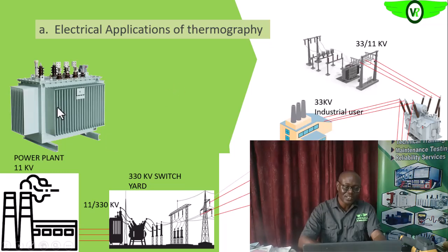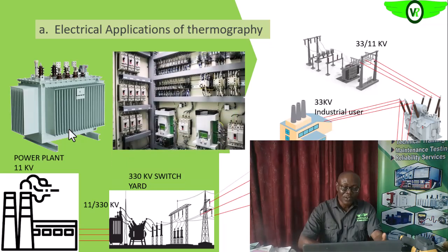All these fins, if they are blocked, the thermogram will show that the fins are cool because they are blocked. So no hot fluid is flowing through or into them. Are you getting it? So that will tell you that something is happening. You have to do something to remove whatever debris is blocking those fins. Okay, so on panels too, electrical panels, you can look at it, but we'll see the thermograms later.